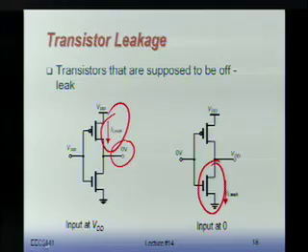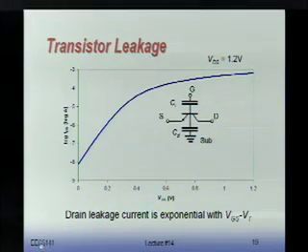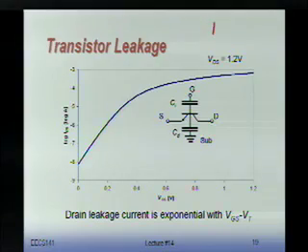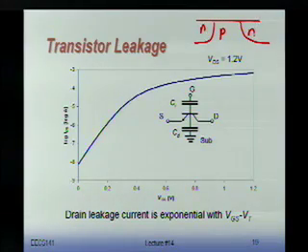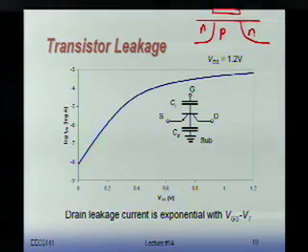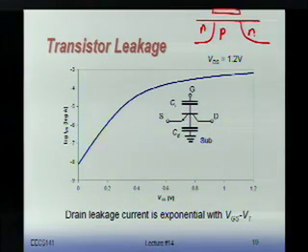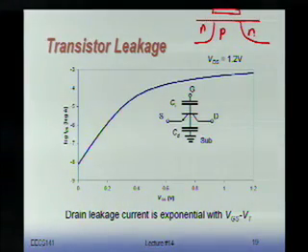Now, why is that the case? Well, I mentioned this already before, but if you look at your transistor, let's say NPN, and your gate, well, you see that obviously when we have a voltage, V gate applied, which is smaller than the threshold voltage, I won't have a channel. There's no conducting channel. So the transistor is literally off.